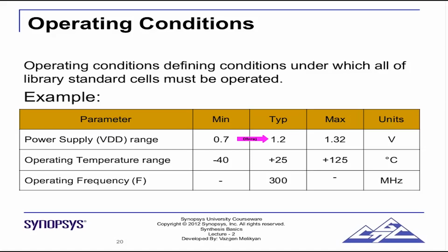The power supply will go through certain things before reaching your design, or before reaching the cell in your design, in particular it goes through a number of meshes. It goes through pads. It goes through the connecting wires. So there will be a power supply drop, there will be an IR drop. So typically the voltage that you get at your design VDD is slightly lower than the VDD applied outside.